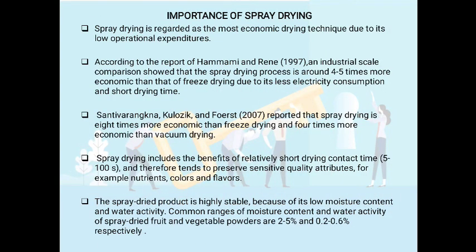Importance of spray drying. Spray drying is regarded as the most economic drying technique due to its low operational expenditure. According to the report of Hammami and Rene in 1997, an industrial-scale comparison showed that the spray drying process is around 4 to 5 times more economic than freeze drying due to its lower electricity consumption and short drying time. Santi Bargna and team in 2007 reported that spray drying is 8 times more economic than freeze drying and 4 times more economic than vacuum drying.